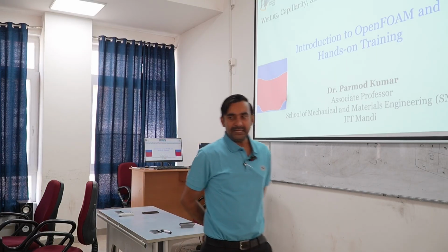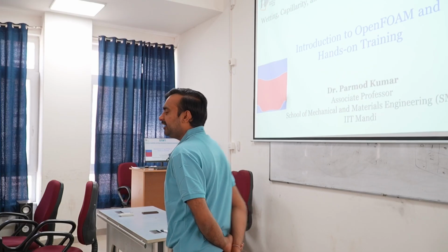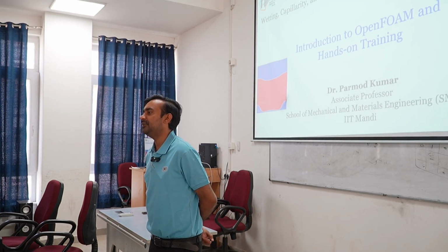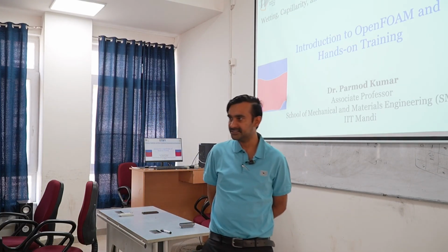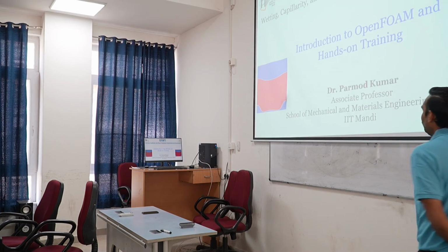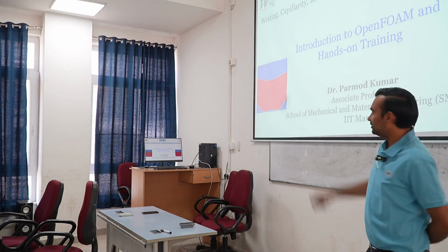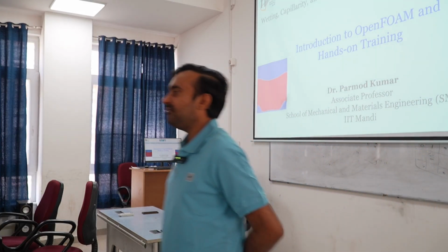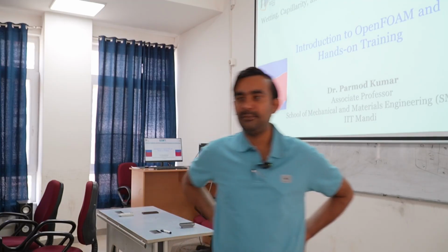But the value of the flow Mach number which we will be considering for our case will be less than 0.3. So that's why we will be doing incompressible flow analysis, because the density change of the air will be very small for the given flow conditions. Now, whenever we solve the governing equations, because I am taking the help of the computer, it means I am numerically solving these governing equations.